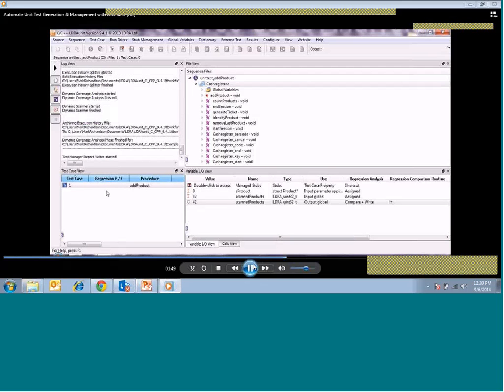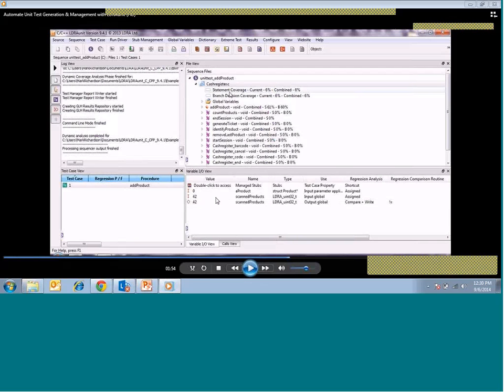Of course, the input for the functions is based on the specification of the requirement, so that we'll get the appropriate coverage where multiple statements within the function are being triggered. And you can see here there's a coverage, statement coverage, a branch decision coverage. The current one is 6%, combined MCDC 6%, current is 6% for branch or decision for that particular file, the entire file, and for that function you can see statement coverage 61% it has hit, and the branch has 60%.